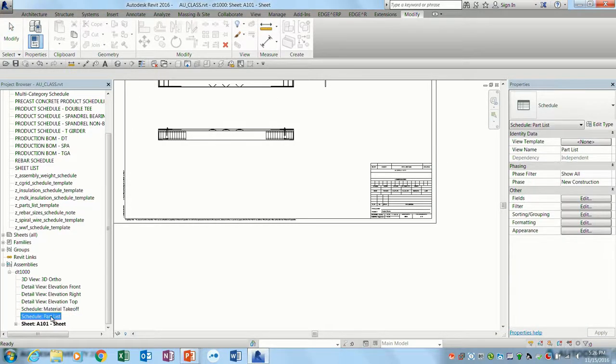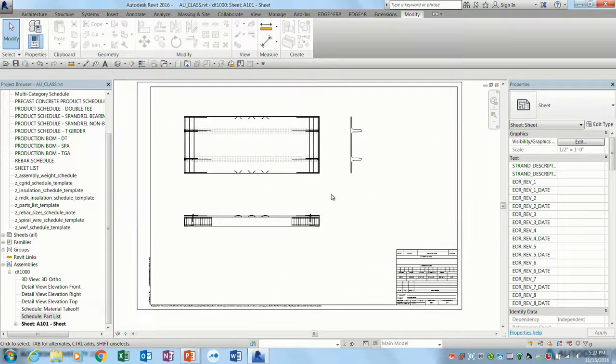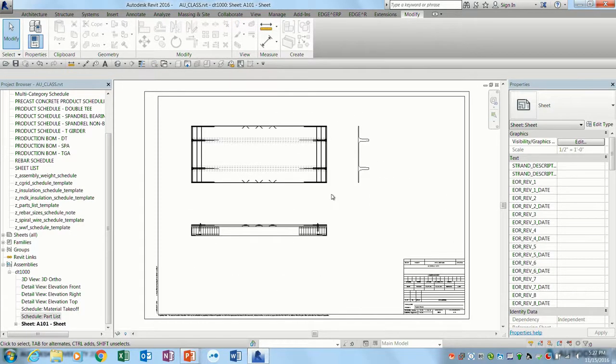Which one? Dimensioning? Yes, manual process as well. Revit dimensions are pretty good, and one of the things I think is great about them is if something changes, the dimension is smart and stays attached to the references. So if the references change, the dimension string changes. So there is that advantage of Revit, in the sense that even if you're doing that work, it's not for naught necessarily. Okay?